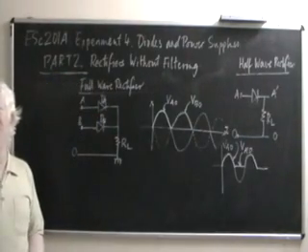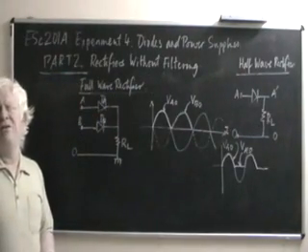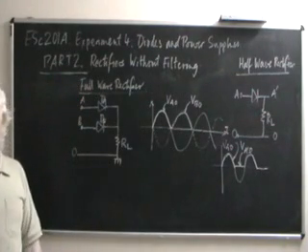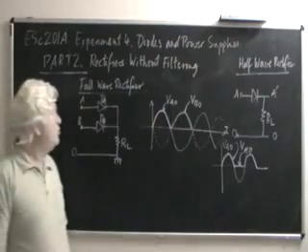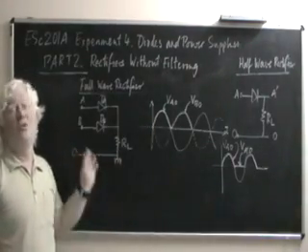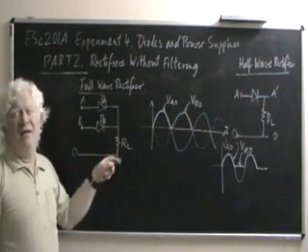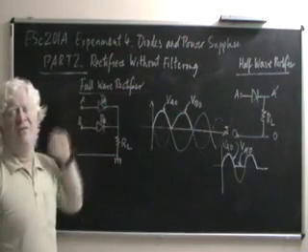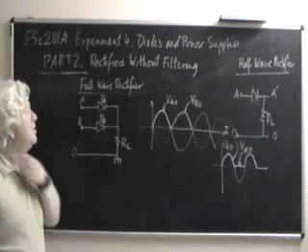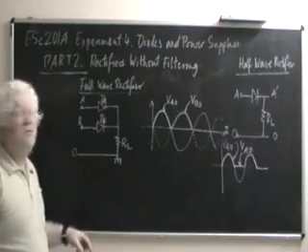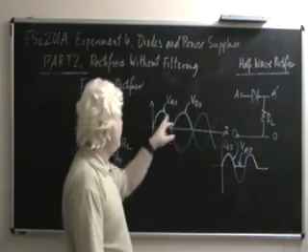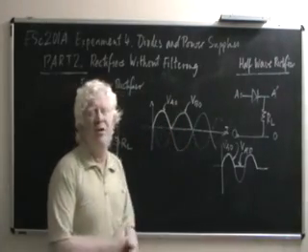So in the second half of one cycle, the second diode DB conducts and allows, because this sinusoid is symmetric, the same amount of current to flow through RL as DA allowed in the first half cycle. So the current through RL, which is proportional to the voltage across RL, follows this pattern that we see over here.